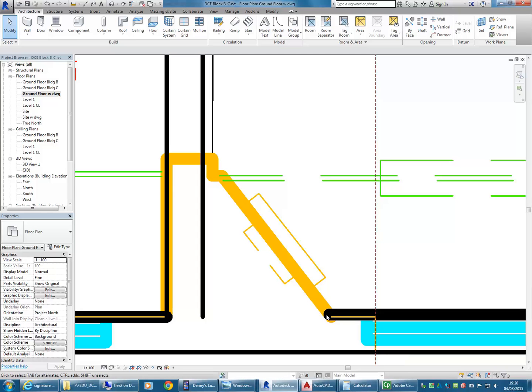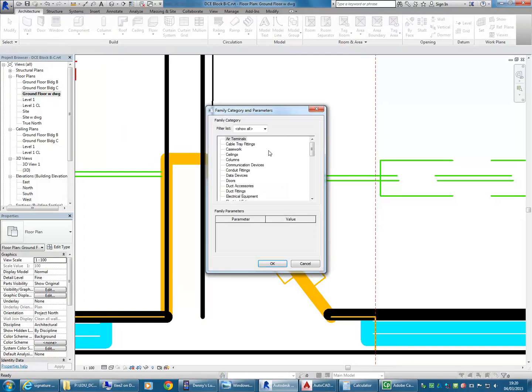But if you want to have a solid triangular section of wall like this, sometimes it's easier just to go to model in place and make an extrusion. Set it to the walls category. Right, so this is hopefully good practice with those basic modelling things that you should all be okay with, because that's something you do in the earlier subjects. If you're not, spend time with it.